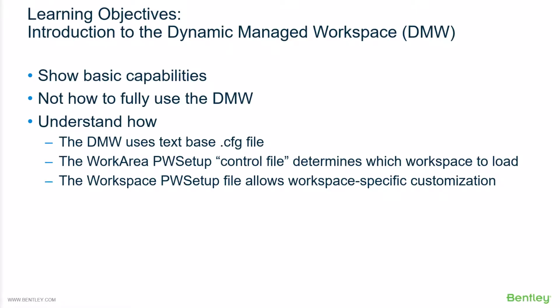You have now been introduced to the Dynamic Managed Workspace. You have seen some of the basic capabilities. You may not be able to fully configure it, but you should at least have an understanding that the Dynamic Managed Workspace uses text-based configuration files. There is a work area PWSetup that can be used as a control file to determine which workspace is loaded. And the WorkspaceSetup file allows workspace-specific customization.